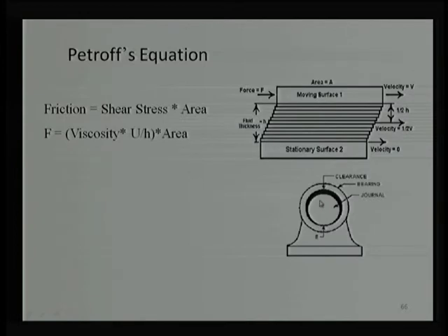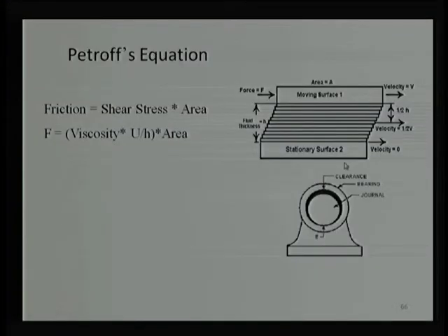It was generally for one fluid film bearing. We can develop a similar relation for all other bearings, or we can open up the complete circumference, the old circle, and develop the surface something like this. So, we can calculate what the friction force will be at this interface. The friction force F can be given in terms of viscosity, velocity per unit of film thickness, into area.